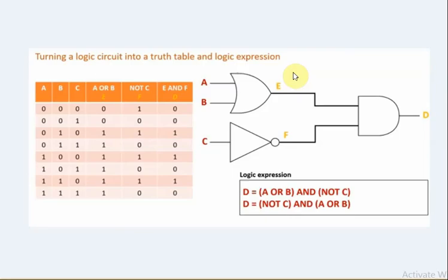According to the problem, you should be able to see, always you separate the branch. One branch is solving the problem, then you need to assume if the firefighter is not doing anything also, this should work. At the same time the firefighter should be involved in the circuit. So you can place an AND gate and say if he is just waiting, this needs to be 1 or this to work. So he should be forcefully off also. Then whenever he inputs a signal, this should go off.